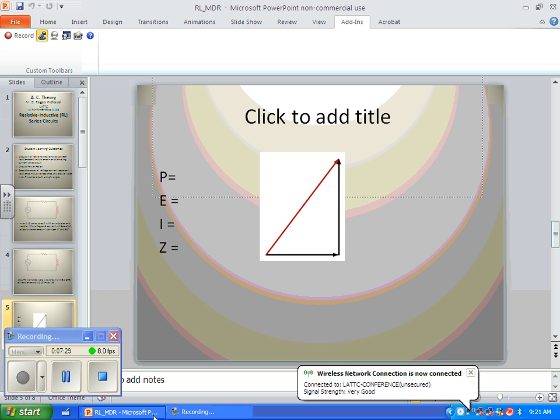The cosine of this phase angle is called the power factor, and that's because it tells you how much of the incoming apparent power is going to be converted to true power, in other words, real work. So how much real work the circuit is doing. Now, I'm not including friction, heat, things like that. Just the pure electrical efficiency all by itself is known as power factor. Very important thing, because a motor can't be more efficient than its power factor, but it can be less efficient than the power factor, right? Okay, so we want to have a fairly efficient motor.